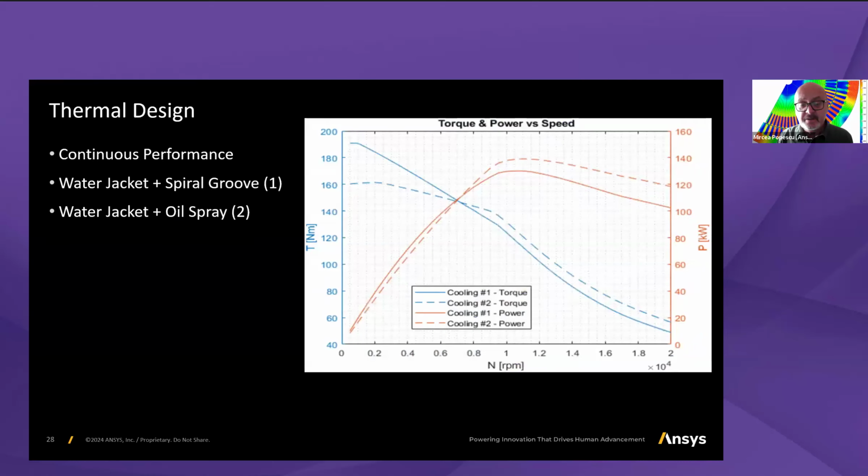And with this configuration, if you look to continuous power, what is it? Continuous power is what we consider the machine performance that is achievable without exceeding a certain temperature limit. For an induction machine, obviously, the two elements, or three actually, but the main two elements that we consider from the thermal point of view and are critical from this point of view is the insulation of the stator winding.